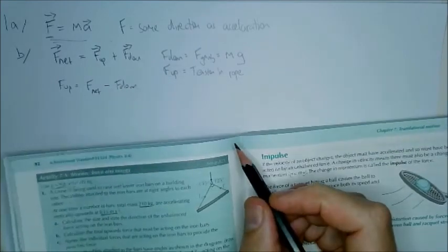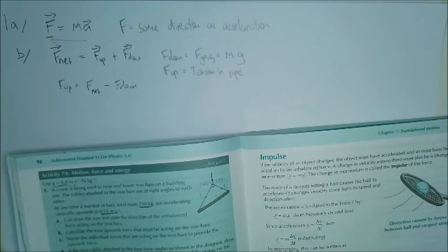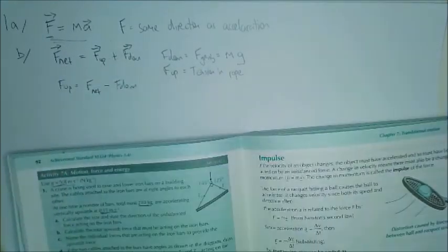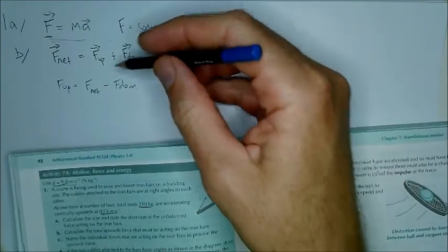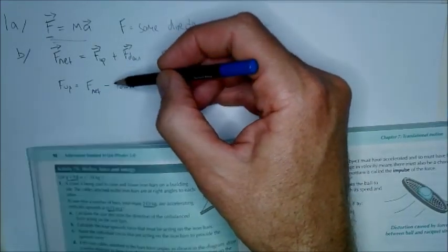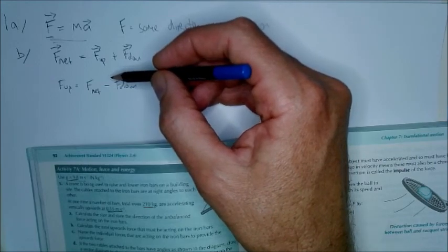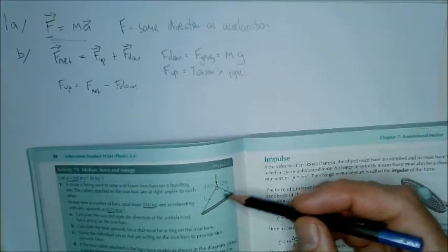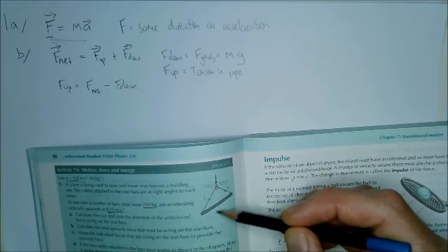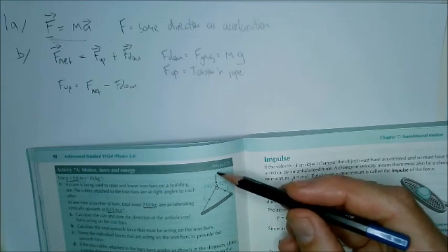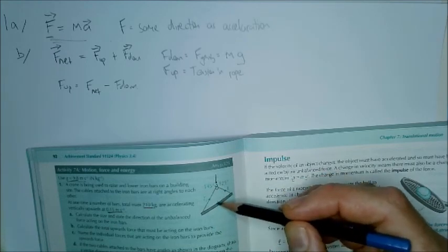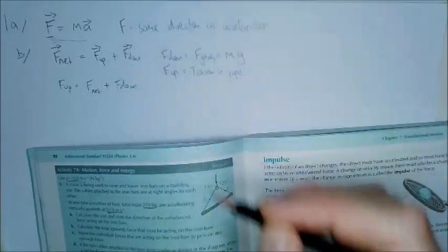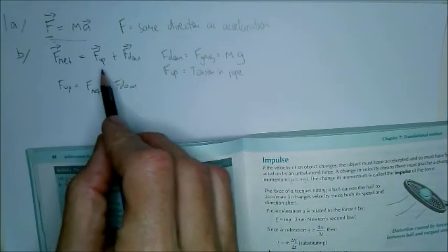Now it's not quite right, is it? What I've actually got is I've got directions here, so these are in different directions, opposite directions in fact. What we need to think is that overall we're looking for an F net that is positive, is higher, is going to be added on, because what you've got is the force from gravity pushing down, but the actual acceleration is up, which means that the upward force on this main rope here must be higher than the gravity force. So let's add the two together instead.